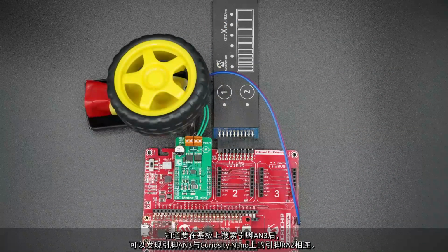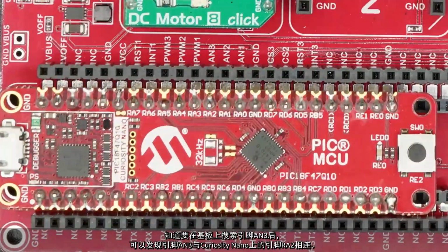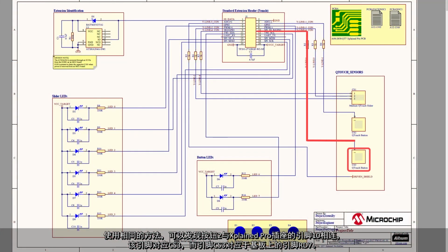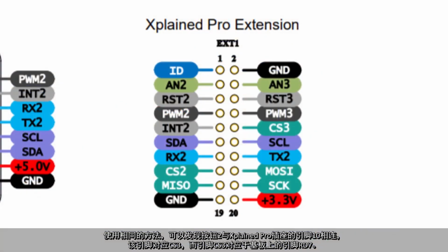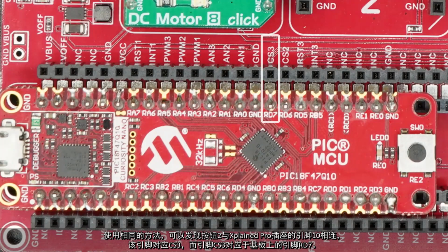Once I know that I am searching for pin AN3 on the baseboard, I can see that pin AN3 is connected to pin RA2 of the Curiosity Nano. Using the same technique, I can see that button 2 is connected to pin 10 of the Xplained Pro header, which corresponds with CS3, and the CS3 pin corresponds with pin RD7 of the baseboard.